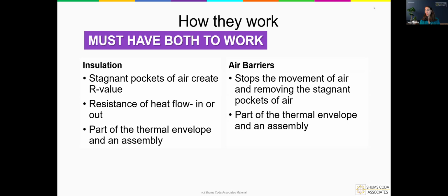So insulation. The big thing about insulation is it's there as the thermal resistance, keeping the heat from either leaving the structure or keeping the heat from entering the structure. And it gets that thermal resistance, and we measure that with the R value.